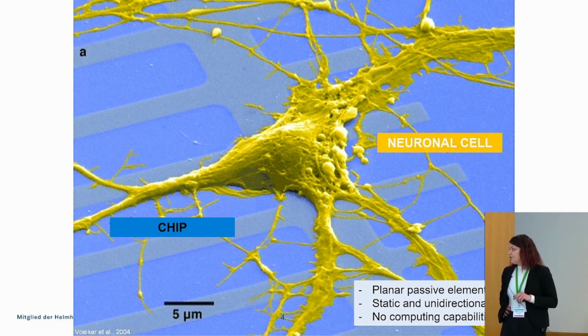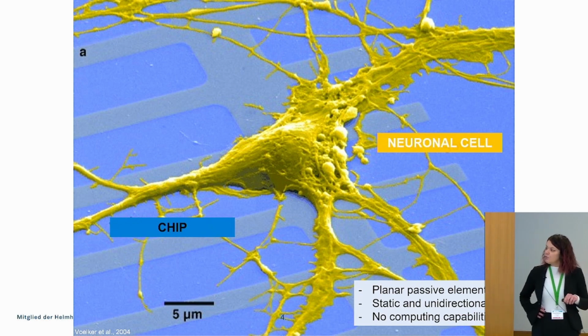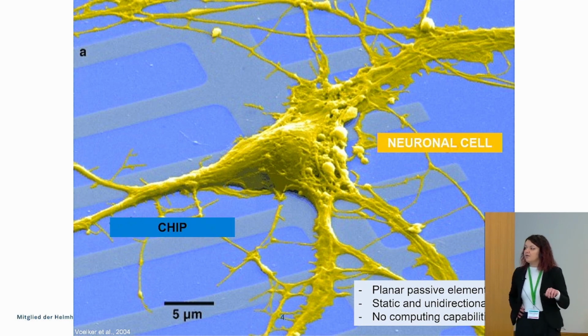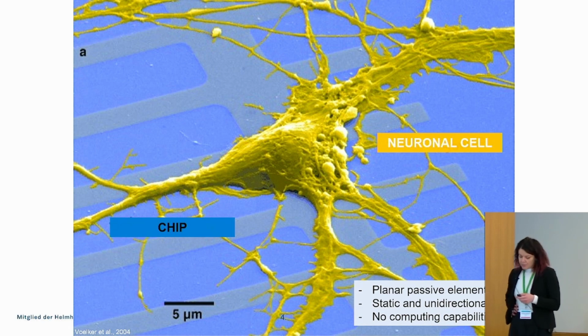And so what is very important here is that the electrolyte contains ions, and of course in the case of PEDOT:PSS, it is a p-type material. We can then trigger the movement and migration of those ions from the electrolyte when we apply a bias at the gate. And based on how many ions are penetrating into the transistor channel, an electronic current is generated and modulated over time, also depending on the transconductance of the channel itself. So this is the typical way our PEDOT:PSS transistor works.